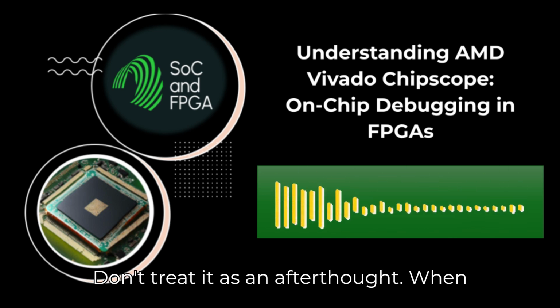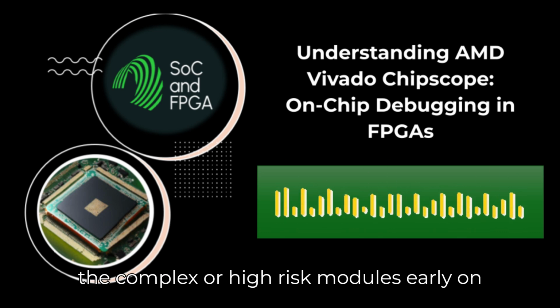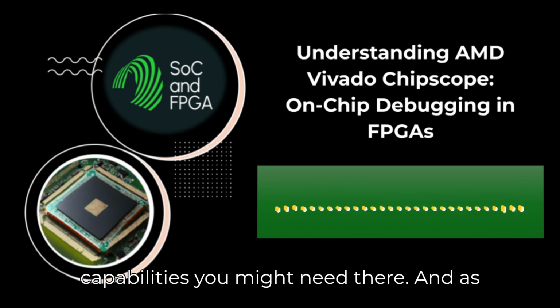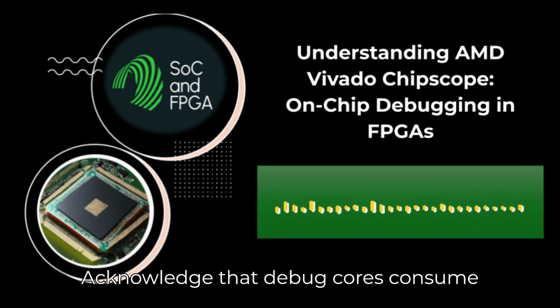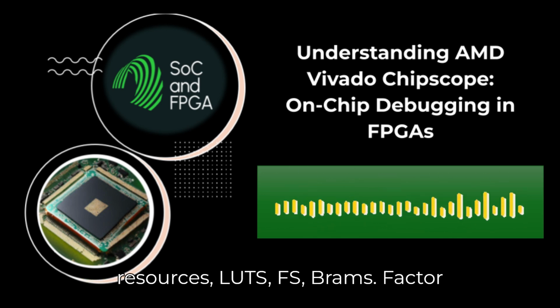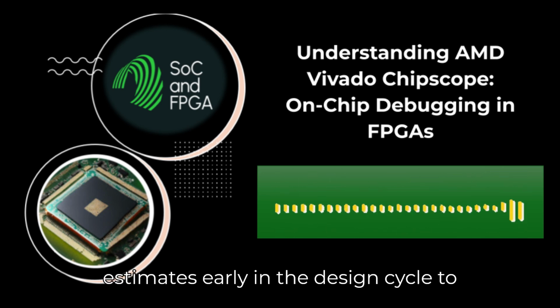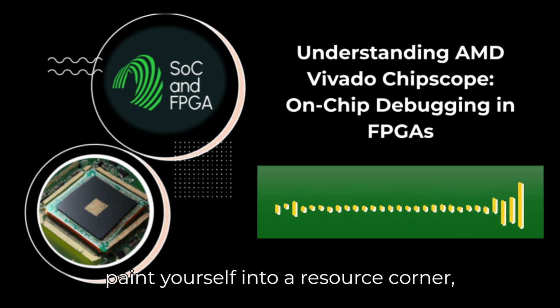Second, plan for debug from day one. Don't treat it as an afterthought. When you're architecting your design, identify the complex or high-risk modules early on and proactively think about what debug capabilities you might need there. And as we discussed, budget for the overhead. Acknowledge that debug cores consume resources, LUTs, FFs, BRAMs. Factor that overhead into your resource estimates early in the design cycle to avoid hitting constraints later when you desperately need to add debug. Don't paint yourself into a resource corner.